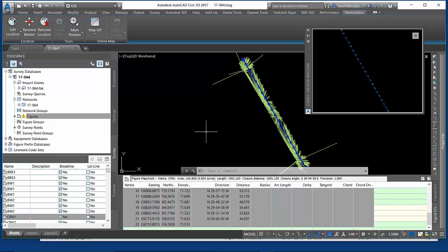So the other thing that I typically do, we're not going to cover here, is I almost always make a completely raw surface disconnected from the survey database of what came in the beginning so I can compare that to my final edited result in Civil 3D.